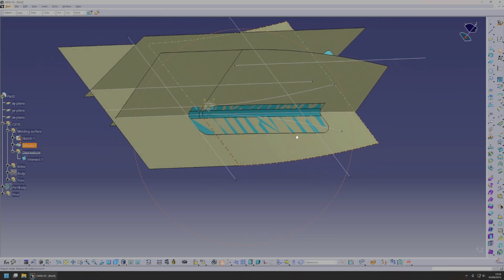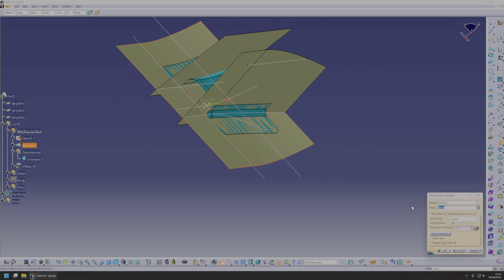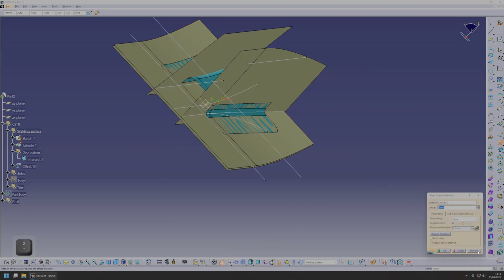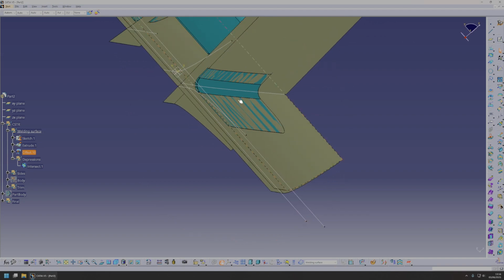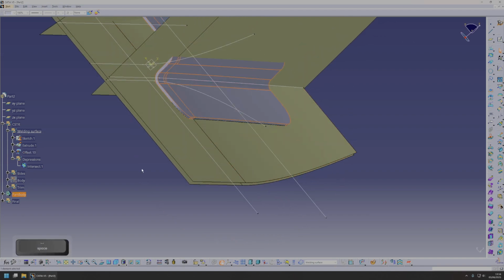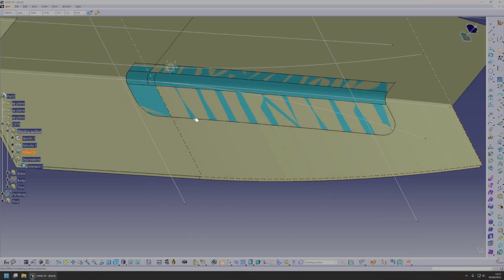That is fine. First, what we needed to do in the first place was to use this one. Go back to here, welding surface, select this. This will automatically replace this command and offset it by 2 millimeters. The other way. Good. So this is now offset by 2 millimeters. Part has been updated as well, with no issues. And this curve actually you need to intersect it without the offset, intersect the original extrusion, and we're going to build on this one.